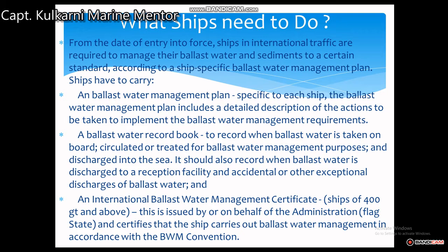That is, when the vessel comes at the berth, we directly pump it ashore and they carry out a treatment. It also records an accidental or exceptional discharge of ballast water, in case of heavy weather or some damage to the ship, or to save lives, when we have to exceptionally discharge that ballast water.